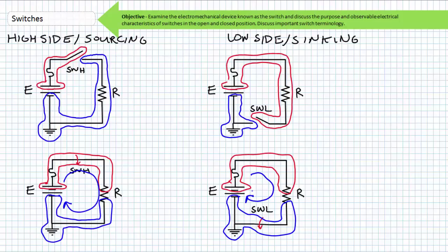Conceptually, a high-side and low-side switch do the exact same thing, though in practice, you'll most often see high-side switching arrangements because of their inherent safety characteristics, due to customary grounding of the negative terminal. When the negative terminal of a source is intentionally connected to ground, there exists the possibility that an electrical load in a low-side switching arrangement can unexpectedly energize without closing the switch.